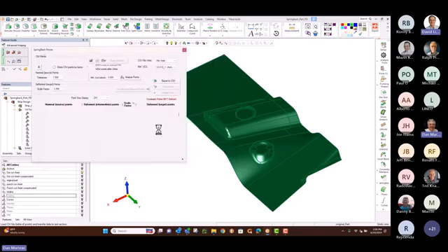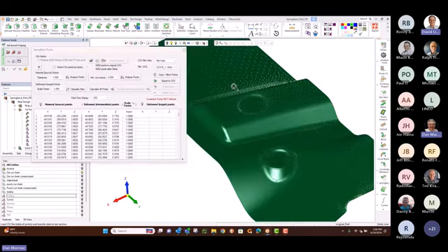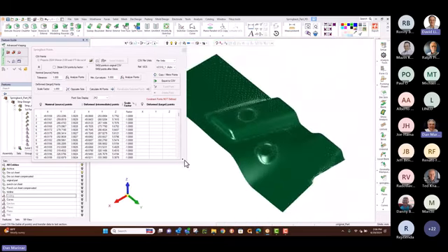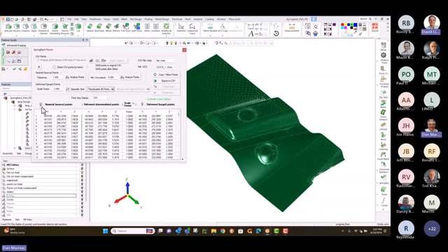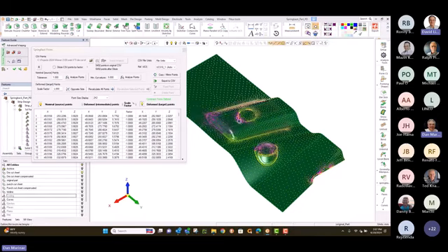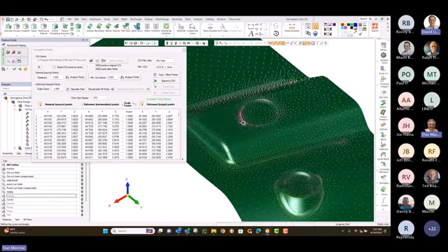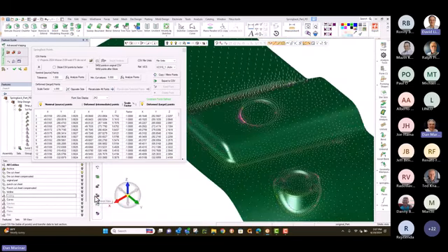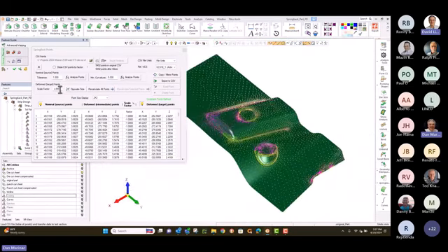This is basically a one-hit look at what could happen with our springback. Those little vectors you see in white are showing you the movement of the material. We could go ahead and calculate that. We want to calculate it opposite side. So instead of warping it further away, we warp in the opposite direction. And those little arrows there, or little light bulbs that I just clicked on, help me see what's happening. So I got the white vector direction coming off that yellow dot, purple dots in the opposite direction. So I know for sure that I am doing the opposite, or I'm compensating for that springback.